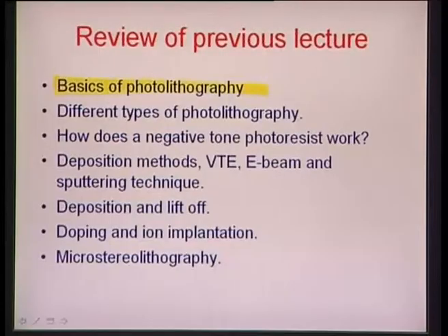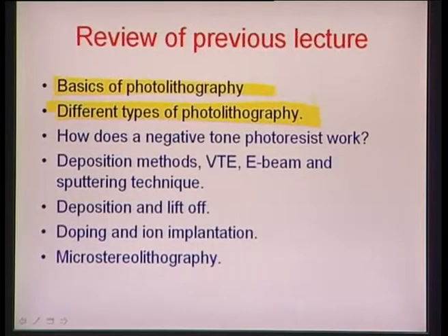We also discussed different types of photolithography: contact, proximity and projection modes, wherein depending on the requirement and the usage you could determine whether you want to go away with expensive optics, or make the optics simpler and go away with touching the mask every time to the resist surface. The conclusion was that projection systems are much more expensive and it's more difficult to create high resolution in comparison to contact mode. All the laboratory research work is done using contact photolithography.